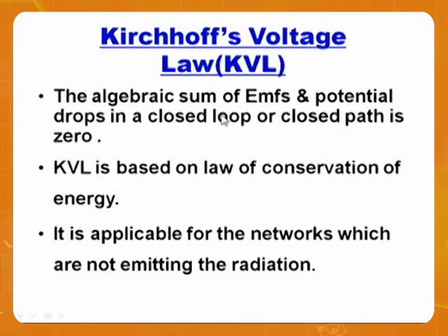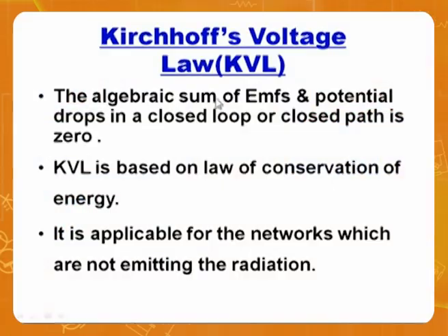The current in the capacitor is 0, but in the circuit, current flows when you use a capacitor. Therefore, we may not call that a closed loop, but we'll call it a closed path. This is a special name given when there are elements like a capacitor available in the circuit. That's why the algebraic sum of EMFs and potential drops in a closed loop or path is 0. KVL is based on the law of conservation of energy.